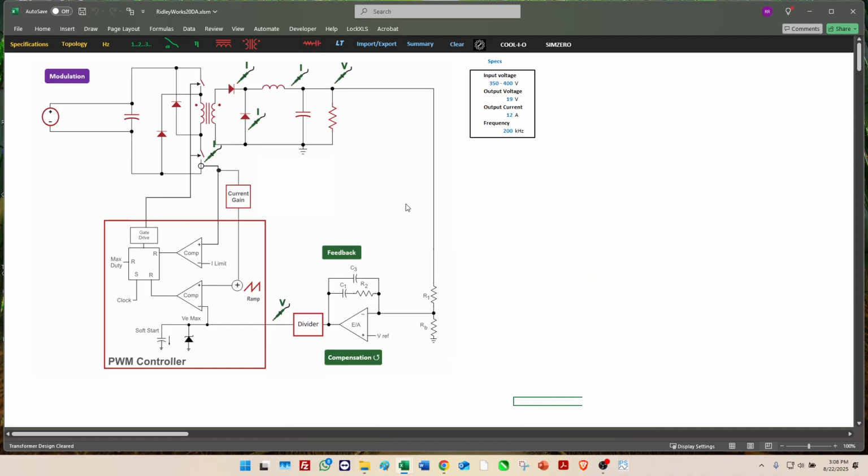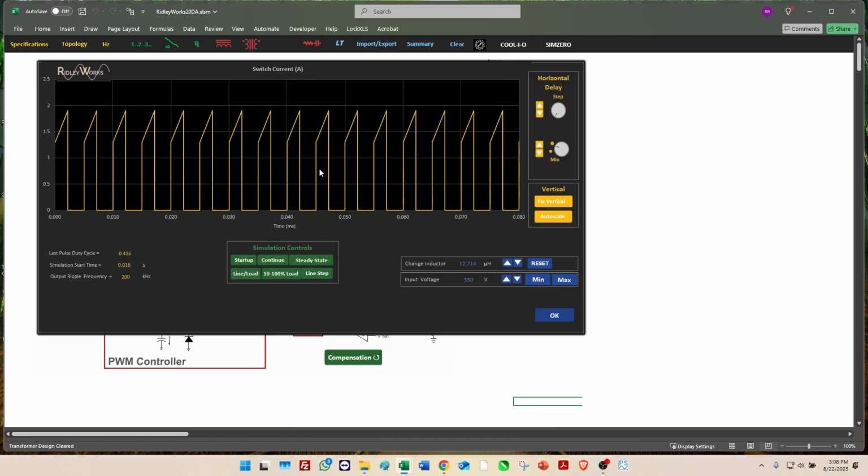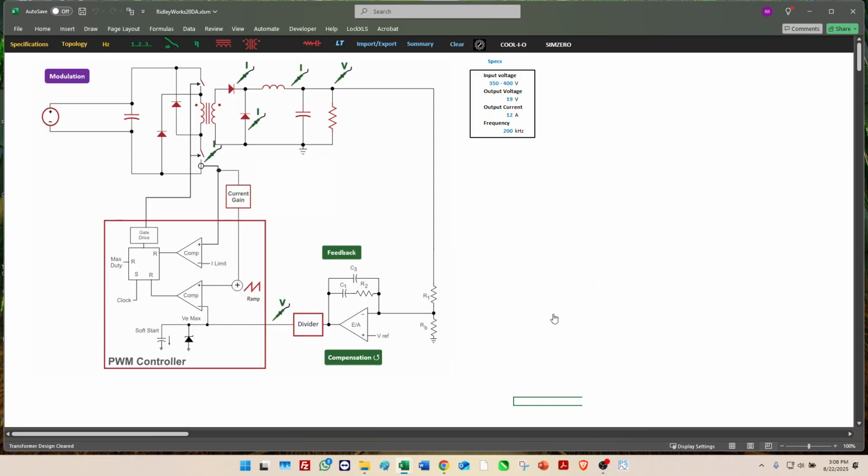Here's the design. If you watch the previous video, number 7, you'll see how we designed the inductor for this converter. Now we're working on the transformer, so we can look at the currents that we're seeing in this transformer. Primary currents are quite small because we've got a 400 volts input, but you see we have almost 2 amps of primary peak current there. Our waveforms have lots of AC component here, no DC of course, being a transformer.